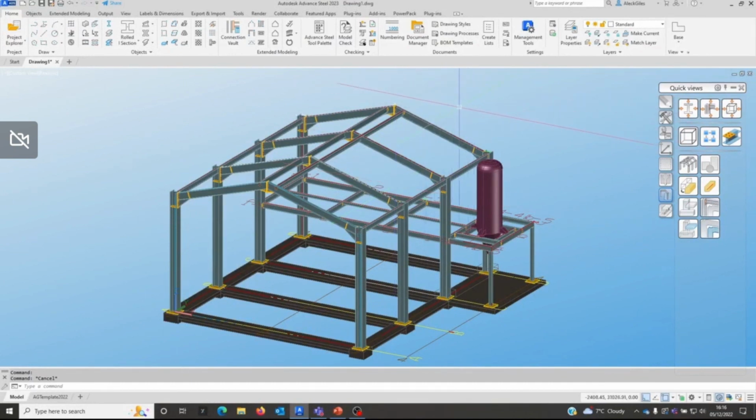So after I fire it up and open a model, I'd immediately go to a beam and hover, so I get the rollover tooltip pop up. Otherwise, if I hover over a plate or a special part as the first thing I do, it breaks the rollover tooltips, and none of them will work properly for the rest of that session. You have to close and restart Advanced Steel.